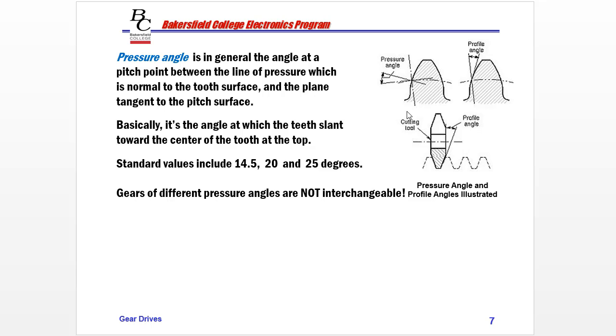And in some conditions, it will lock up that gear set and prevent it from moving and cause damage to the system, the bearings, the shaft, and even the motor and drive system. So be sure you're using gears of the same pressure angle.